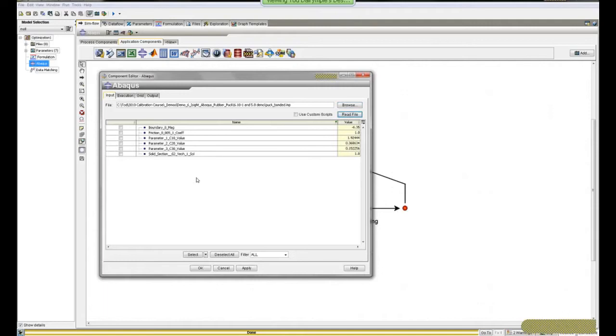It reads down through the input file and quickly shows me these three parameters, and I just click here and say those are three things that I want to use within my Isight process. And you see over on the far right hand side, they have default values as stipulated in my input file. Those are the values that came out of curve fitting, what I'm calling bad data that was tainted by friction. Knowing that that's overly stiff, can we find much better values through this process?